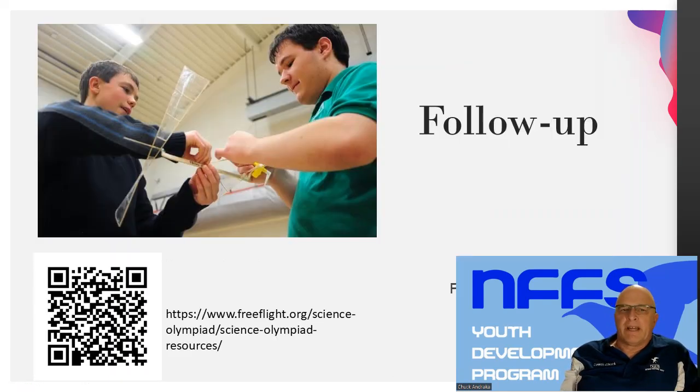That's mostly the basics of building and flying. There's a lot more to it than that, but it gives you some areas you can start focusing on. If you're buying a basic kit and have basic tools, you're going to be looking at your total mass or length of rubber on the helicopter as your primary optimization and learning your best winding techniques. If you have more advanced tools, you can vary your rubber width. You can vary your pitch angle and even your rotor setup. So there's lots of possibilities, but some of them are more advanced.